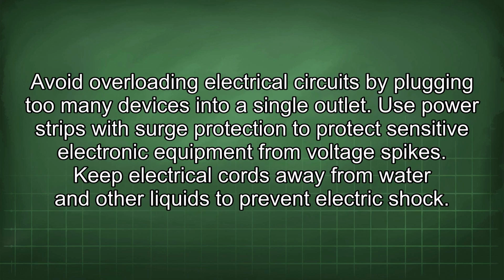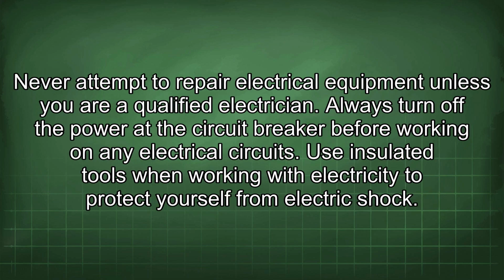Avoid overloading electrical circuits by plugging too many devices into a single outlet. Use power strips with surge protection to protect sensitive electronic equipment from voltage spikes. Keep electrical cords away from water and other liquids to prevent electric shock. Never attempt to repair electrical equipment unless you are a qualified electrician.